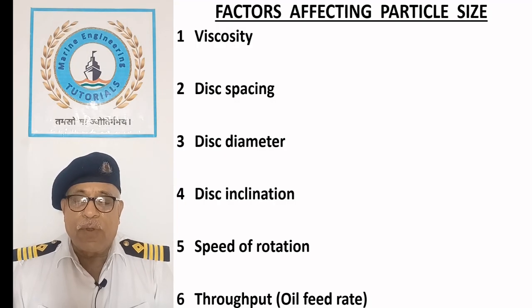This completes our study of the disc type purifier bowl, the selection of gravity disc, the action of particles between the discs, and the factors affecting particle size.